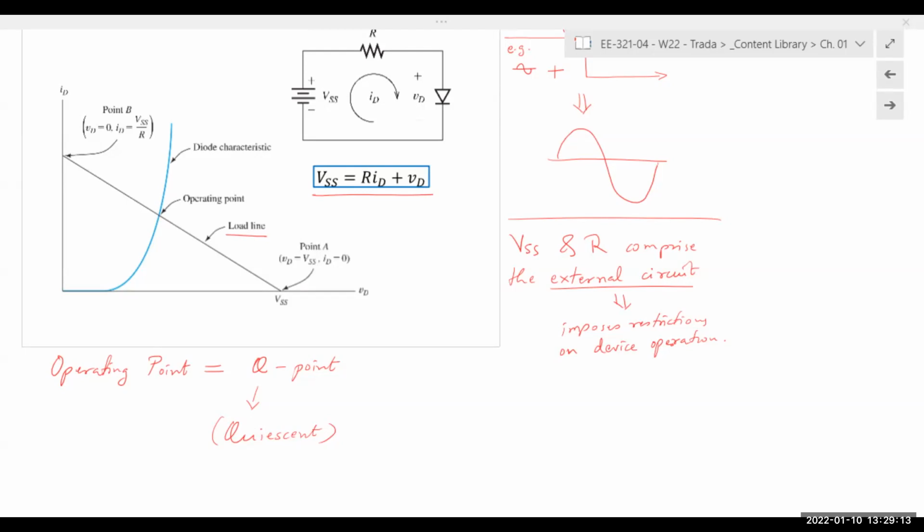The AC signal is a sinusoidal waveform, going from 0 to some positive voltage and then negative. What will happen? The anode is already connected to the positive terminal, but if the AC voltage goes to a positive peak, it applies an even more positive value here. The diode will still remain on.